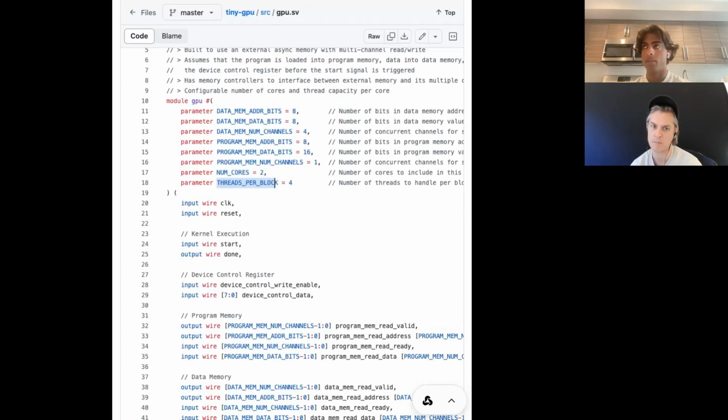And basically every time the clock goes from 0 to 1, registers in the chip, which are like D flip-flops, will take in a new value. And so that creates the way for state. That type of state transfers on the clock. So whenever the clock ticks, it sets the pulse of things happening in the GPU. Generally in each clock cycle, at the start of the clock cycle, some new values are set.